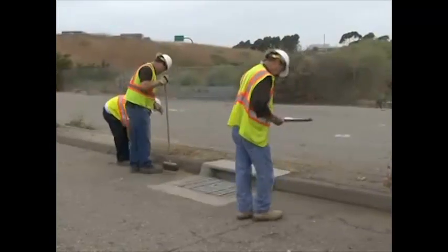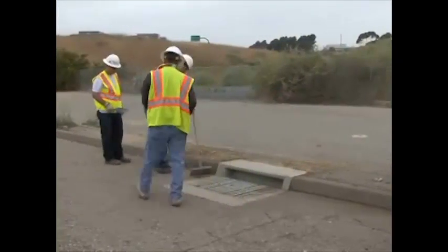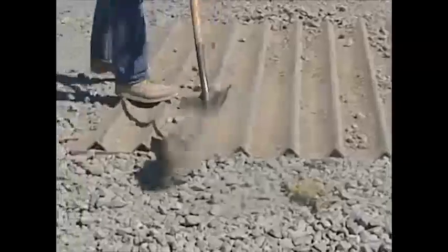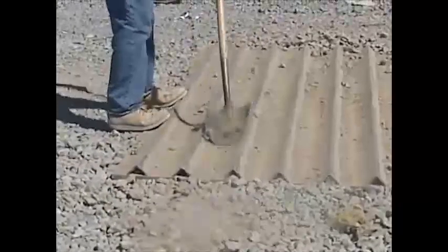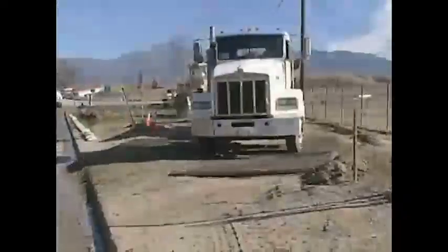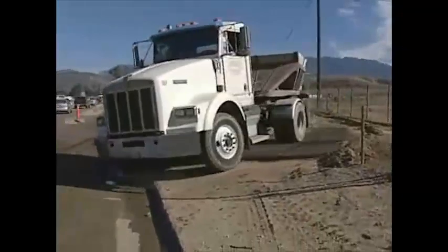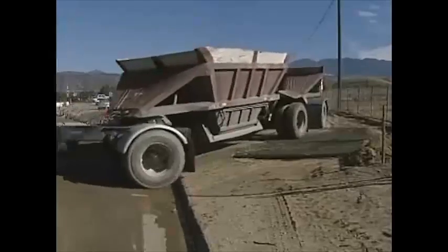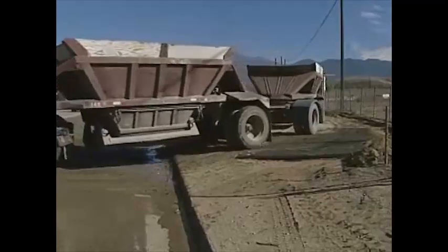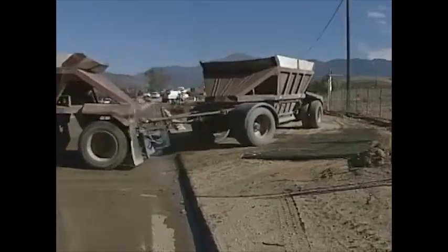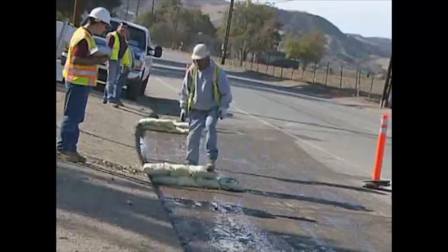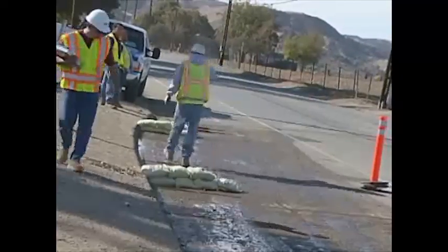Check all roadway ditches and make sure they are kept clear. Check to see if the construction entrance is clogged with sediment. If this occurs, remove the rock, dispose of the sediment, and replace the rock. During some inspections, you may find a stabilized entrance that was installed with the correct length and depth of rock, but was not graded properly, such that runoff is not routed through the sediment trap. If a sediment trap was not incorporated into the design, make a note on the inspection form, follow up with the contractor, and request an immediate corrective action.